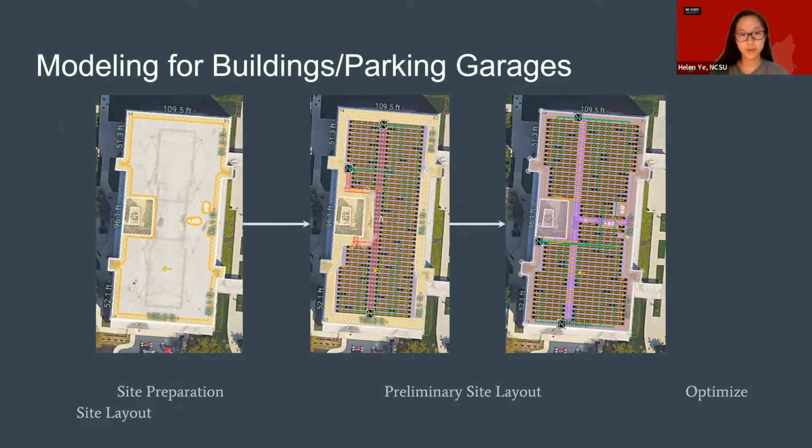Our final layout for the rooftop panels were south-facing landscape panels tilted 15 degrees with a pitch of 16 inches. For the carports, some panels are not set up in rows like rooftop systems. That gave us the ability to tilt the panels a little bit more to more efficiently capture sunlight. After researching and testing the optimal angles, it was decided that carports covering north to south parking was tilted 30 degrees, while panels covering east to west parking was tilted 15 degrees. Once panels were placed, panels were then stringed together after determining the proper string size for equipment.